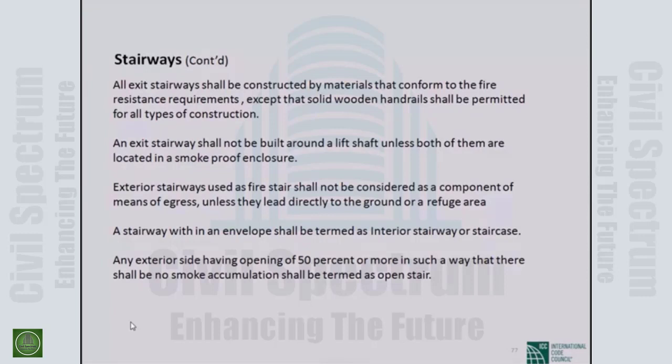But it is not written in the BNBC, it is in the NFPA. Your floor's slipperiness must be such that people don't fall down. The friction factor value is 0.5 for non-slippery, or a value of 0.3 is very slippery. So you have to be careful of the slipperiness. The material we use in tiles is always less than 0.3 if it is glazed; if it is non-glazed, it's fine. Particularly in toilets, we use tiles which are not slippery. You have to be careful about the stair.